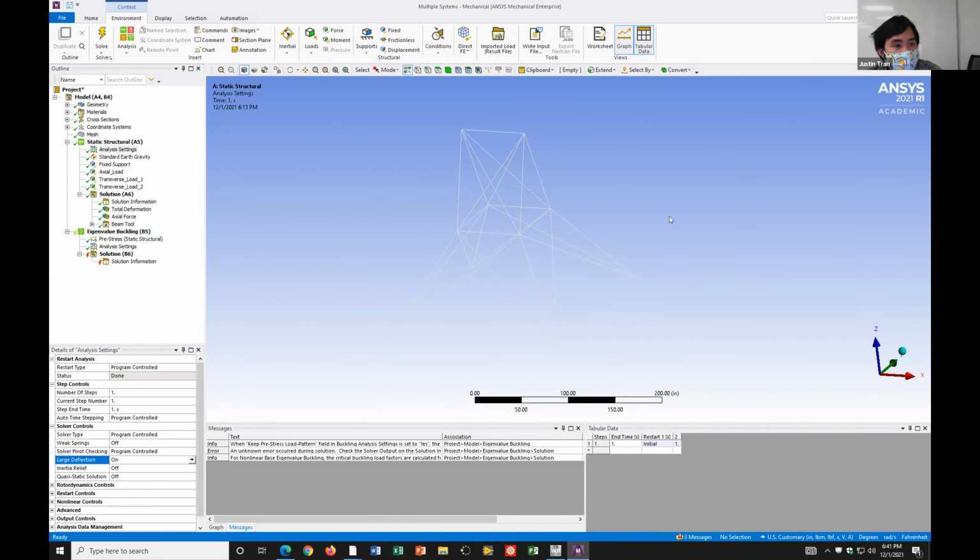Okay, so the deformation fields that are generated in the modes, where it has the higher magnitudes, we basically disregard that as not actually what's happening. Right. You can view those and say that the gearbox or whatever structure you have is going to deform like this, and the shape is going to look like this. But the actual magnitudes of those deformations depend on what kind of loading you apply onto it as well.